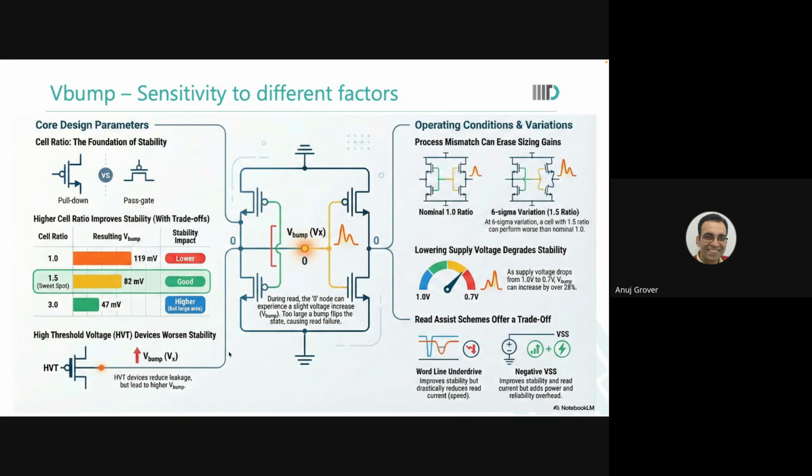See, I can say that because I'm operating at 1.1 volts now, I will use HVT devices. If I was to operate at 0.8, obviously I could not have used HVT devices. So by going to a higher voltage, I have also more flexibility to reduce leakage by other means. I can still say that during standby, I will go to the periphery supply so that leakage reduces in standby. There are so many things I can think of.